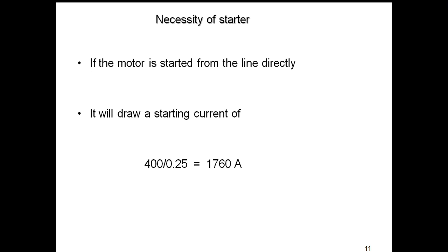Since there is no back EMF and the resistance of armature is low, so the starting current will be very high.